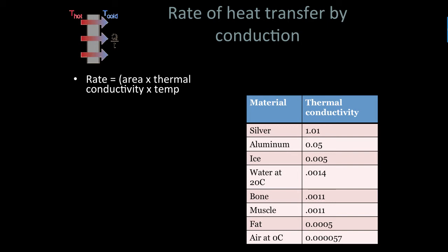Why is down used? Because it traps a lot of air in a lot of air pockets. The down by itself isn't what's giving us the insulating factor. So typically, what we're trying to do is have some way that we can trap some air, because air has that very, very low thermal conductivity, and gives us that insulating effect.